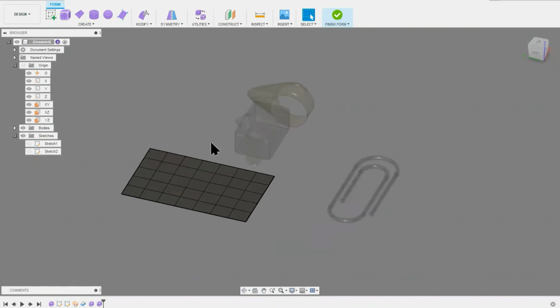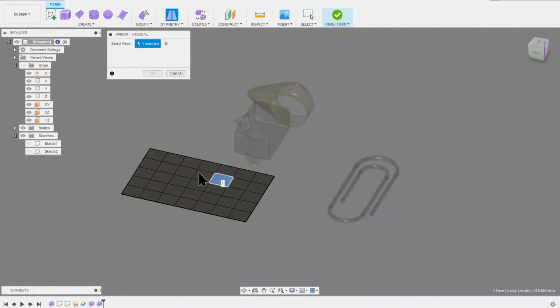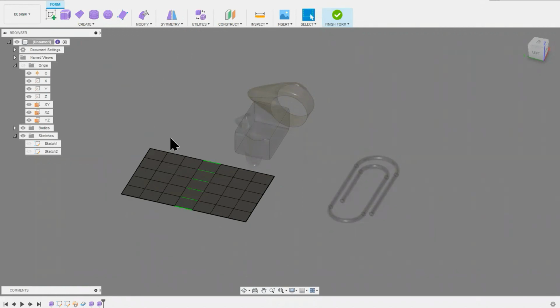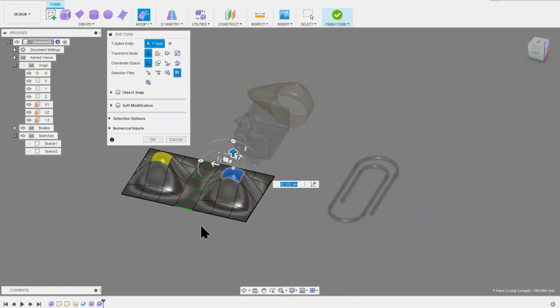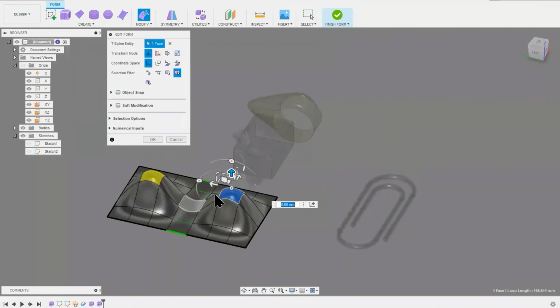Okay. Now, one of the very clever tools with regard to this free-form modelling concept is that we can add symmetry between a multitude of faces as well. So in actual fact, if I wanted my model to be symmetrical, I've got this option here to select two faces, and then what Fusion does, everything that happens one side of this face will happen on the other side. So when we apply a mirror symmetry, if I was now to go and modify the form and select this face and drag it, you'll notice now I get the same option either side of the face.